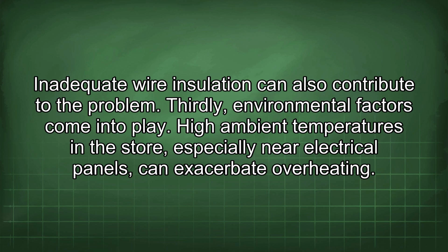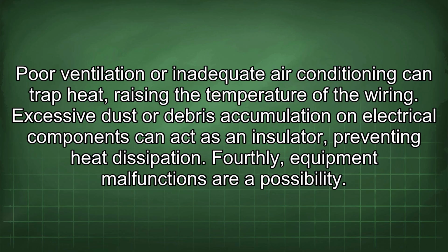Thirdly, environmental factors come into play. High ambient temperatures in the store, especially near electrical panels, can exacerbate overheating. Poor ventilation or inadequate air conditioning can trap heat, raising the temperature of the wiring. Excessive dust or debris accumulation on electrical components can act as an insulator, preventing heat dissipation.